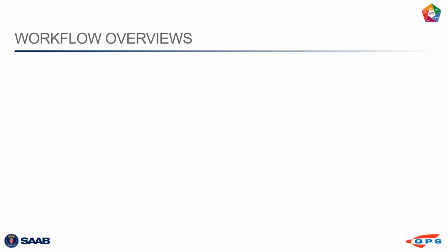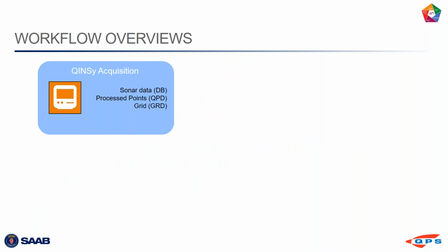Okay, now I'm going to provide an overview of a workflow which is very befitting for today's hydrographic office. If acquiring data in Qinsy, along with all the benefits of the real-time monitoring and QC functionality to ensure optimal data collection, you also have the benefit of the Qinsy DB file, which is a very rich file format. And you can utilize Qinsy's real-time processing, which is essentially using your acquisition time as processing time. So this is by far the most efficient workflow because you're getting the processed points, which are called the QPD files, in the bathymetric grid that's already prepared by the time you get back to the dock.